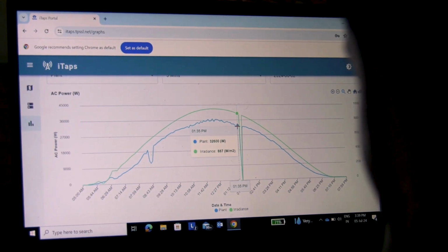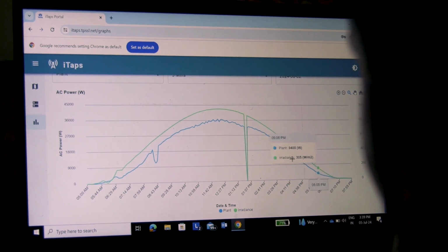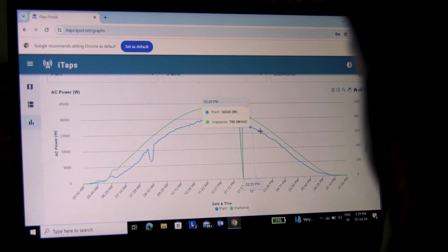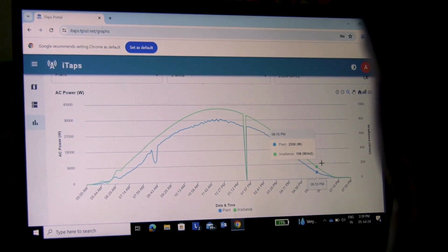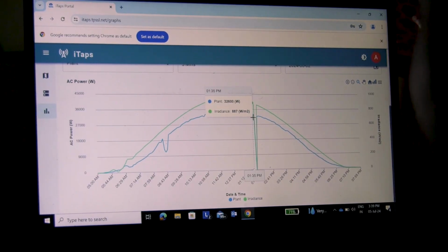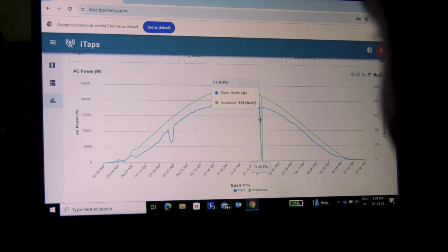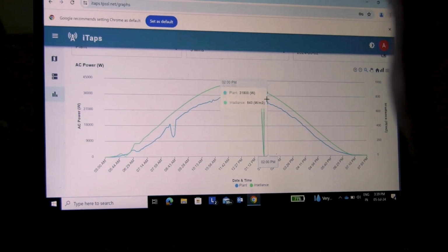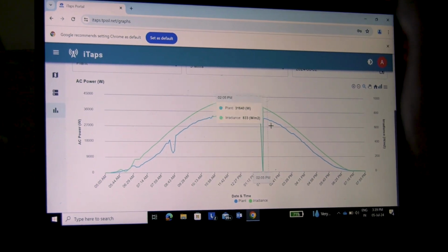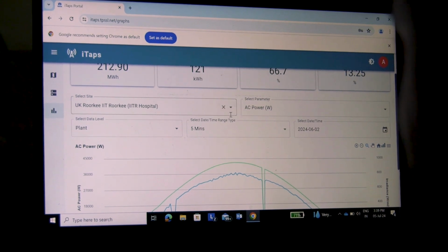The graph exhibits a smooth and consistent rise, indicating clear and sunny conditions. After midday, from 1 pm onwards, both irradiance and power output begin to decline as the sun descends. The decline continues steadily into the evening until both metrics drop to 0 by 8 pm as the sun sets. This graph effectively demonstrates a typical clear day with efficient energy conversion, with a minor dip around 1 pm, likely due to temporary cloud cover or shading, providing essential data for evaluating the performance of the solar power system.